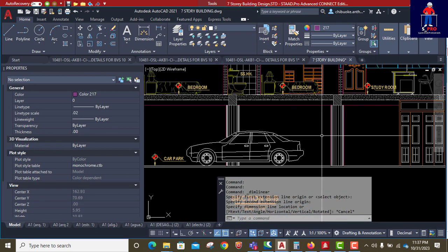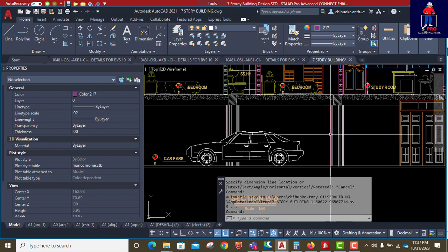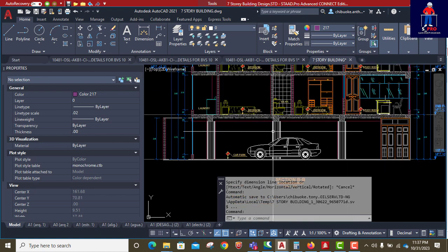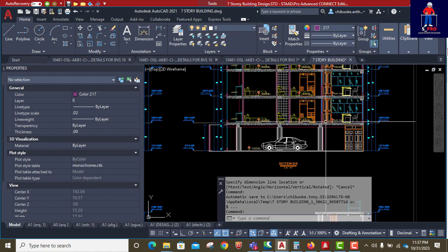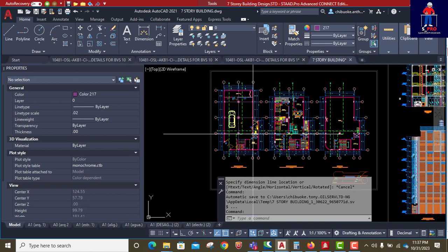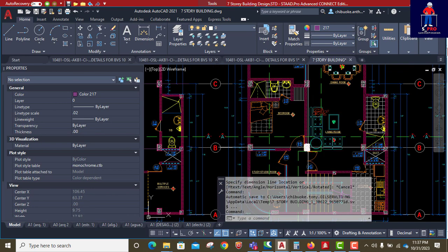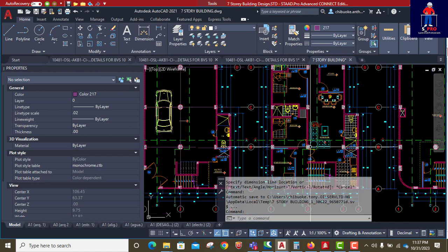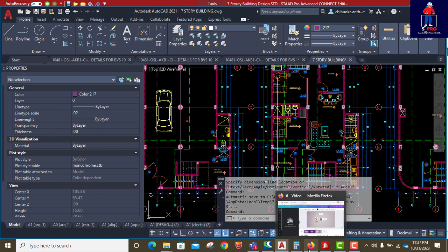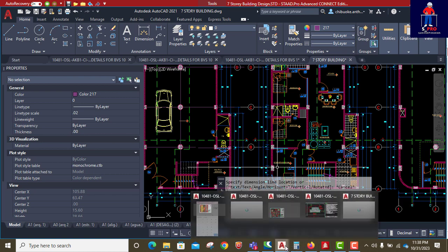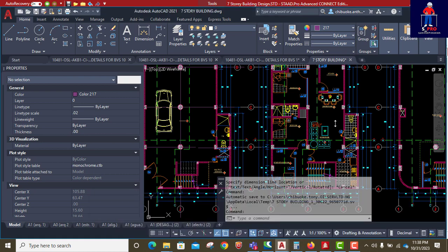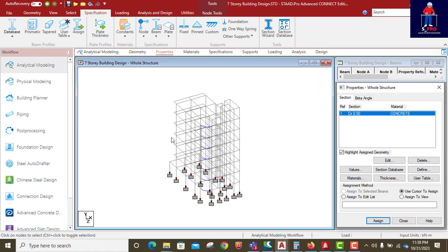I noticed somewhere in the drawing that this circular column stopped at this ground level, so they didn't continue with the circular columns. If you see clearly from here, from the plan, see circular column here. But for these other levels, you see it's no longer circular, it is rectangular. So it's only our ground level we have that circular column, while we continue with our normal square column.